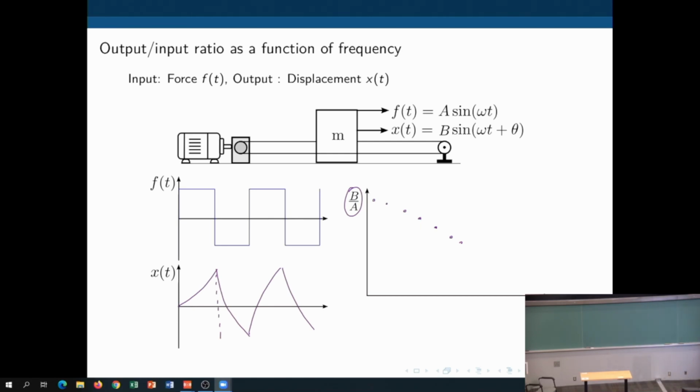And at one point, this will get worse, because now inertia gets in the way. The same thing happened to speed, and this slope here will now increase, and it will go down faster. And that point, when we see the slope changing, that's where the inertia and friction, mass and the friction, will start to play a significant role in the time response.